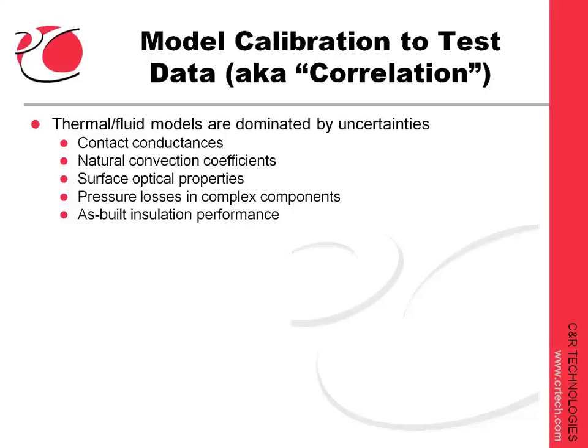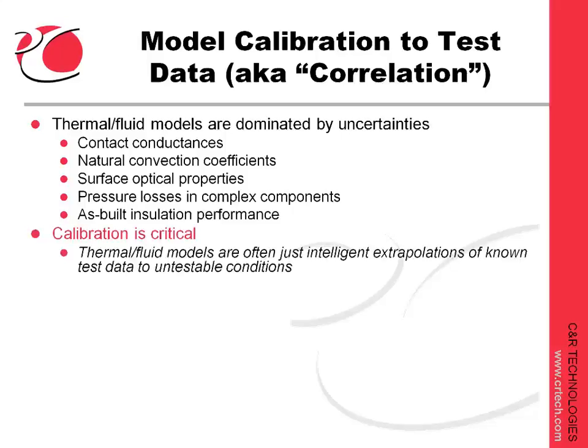hot or too cold. But if we were to take one measurement of the as-built contact conductance, that 20 or 30% collapses to a much smaller number, and not just for the conditions of that measurement, but for nearly all other conditions. So now we can trust the resulting calibrated thermal model when it extrapolates to many other scenarios, most of which we can't afford to test. So model calibration is absolutely critical for thermal fluid models. In fact, you could easily argue that thermal fluid modeling is not really useful at all without calibrating, at least not for finalizing a design.